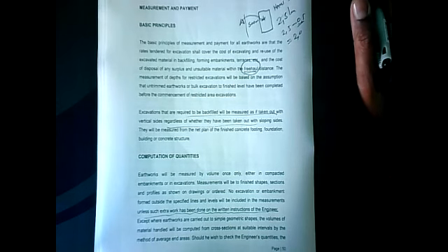Except where earthworks are carried out to simple geometric shapes, the volumes of material handled will be computed from cross sections at suitable intervals by the method of average end areas or any other method that you feel is easier. Should you wish to check the engineer's quantities, the contractor may at his own expense take levels and prepare the cross sections necessary for the measurement and computation of quantities. If you believe that the engineer measured incorrectly, then you can redo the calculations to prove him wrong.